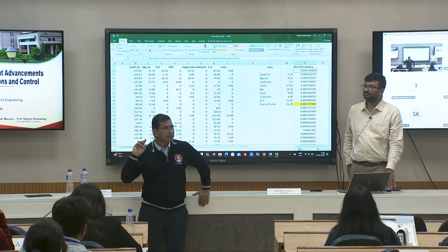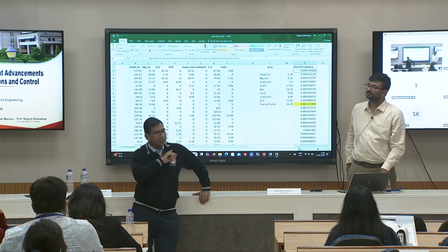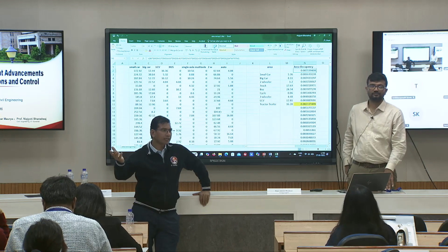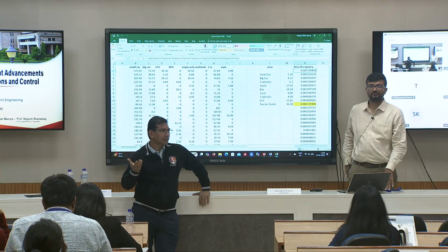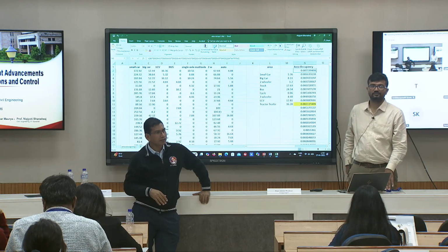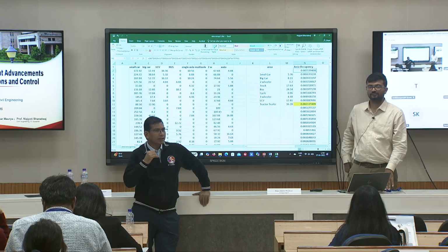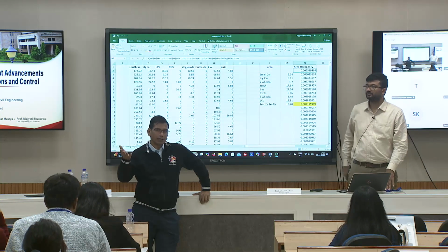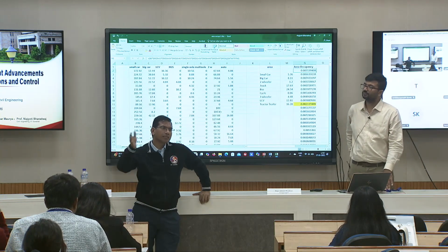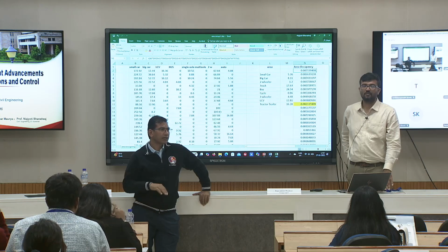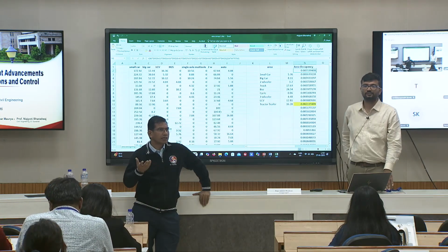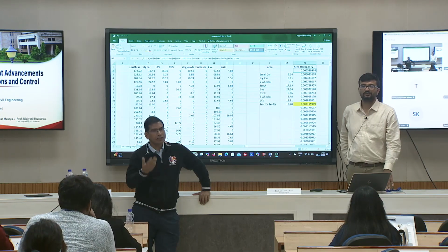All the fundamental relationships, if you draw them with occupancy also, you will get a similar kind of relationship, but the values will obviously be different. Occupancy is in percentage, while density has certain different units. So this is an altogether different thought process of getting another measure of density. It's not a replacement, but you can say it is equally a good measure of whether a particular condition is dense or not.